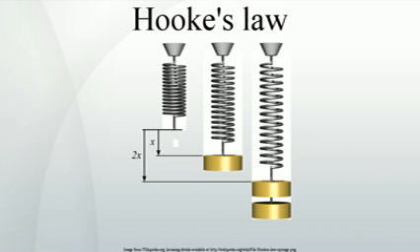Suppose that the spring has reached a state of equilibrium, where its length is not changing anymore. Let x be the amount by which the free end of the spring was displaced from its relaxed position, when it is not being stretched. Hooke's law states that F = kx, or, equivalently, x = F/k, where k is a positive real number, characteristic of the spring. Moreover, the same formula holds when the spring is compressed, with F and x both negative in that case.